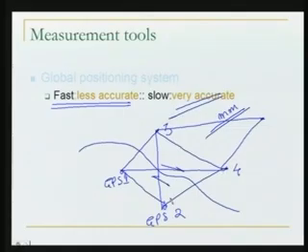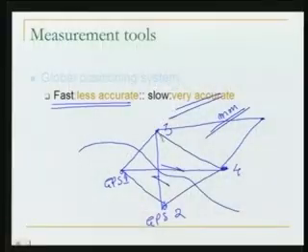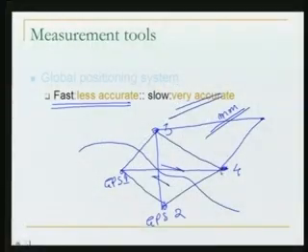Now if there is any relative movement in between these two plates, so these points will move in relation to these two. What the GPS is giving us? GPS is giving us the coordinates regularly. So we know the coordinates of this, so we know this distance, or rather I can say we know this vector. So between 2 points I know the vector.